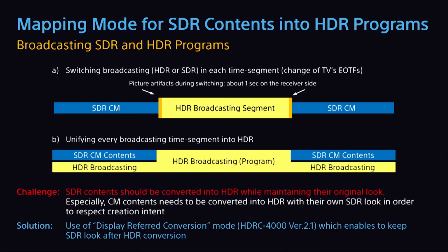And we were thinking of sending a flag in the HDMI. 709, give me the 709 gamma. HLG, give me the HLG gamma. The problem is, when you tell a consumer television to do that, the switching of the gamma will produce artifacts. Sometimes it's 3 frames, 4 frames, it may go black, it will freeze. Therefore, that didn't work.